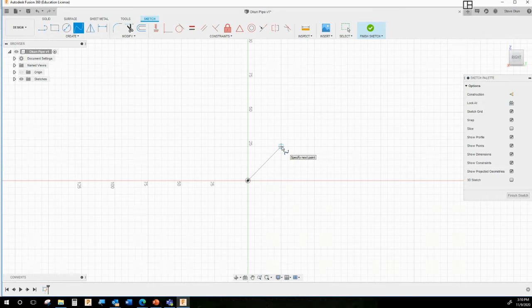But it's kind of like you're putting a push pin in your drawing here. So click there, and you'll notice when you start dragging downwards, it will start curving as if you're pulling a string around that push pin. It will start curving downwards. And depending on how complicated your line is, you put in as many points as you need. So a lot of times designers will use these to trace. They'll import a picture onto their work plane, which you can do in Fusion, and they'll use this to set up points to kind of trace something. So again, it's just as many points as you need.